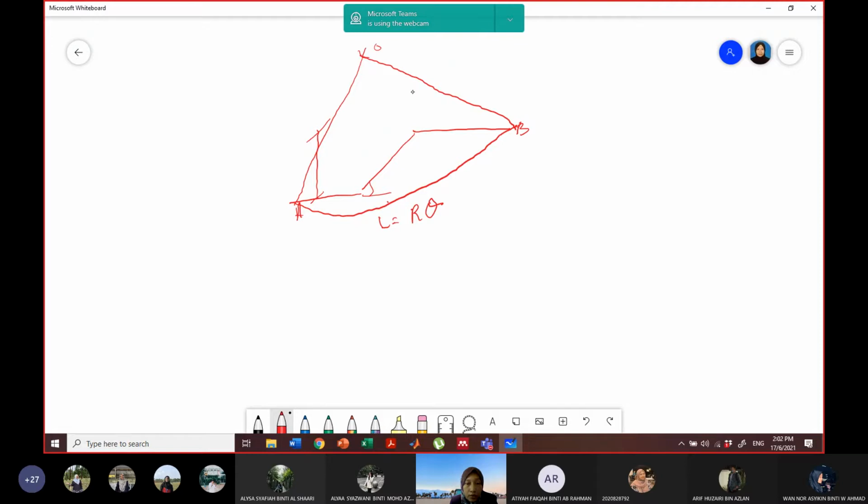Again, just to remind every one of you, let's say we have a slip mass, we have the slip circle, and we have the soil mass above the slip circle as W. So the one unique W here needs to be divided into equal vertical slices, such as we have W1, we have also here W2, and here also let's say we have W3, and the next one is W4, and the last one is W5.